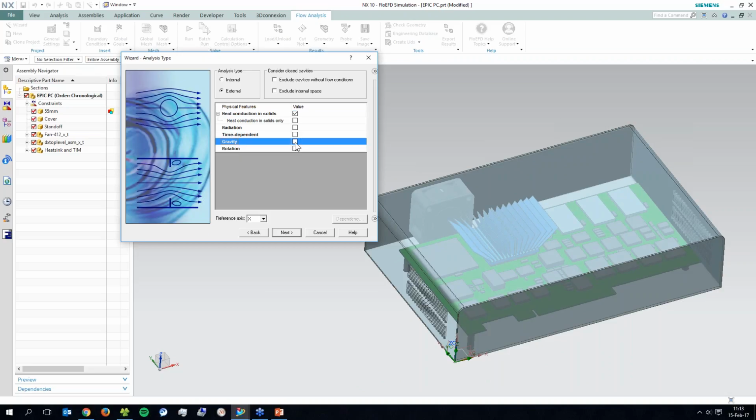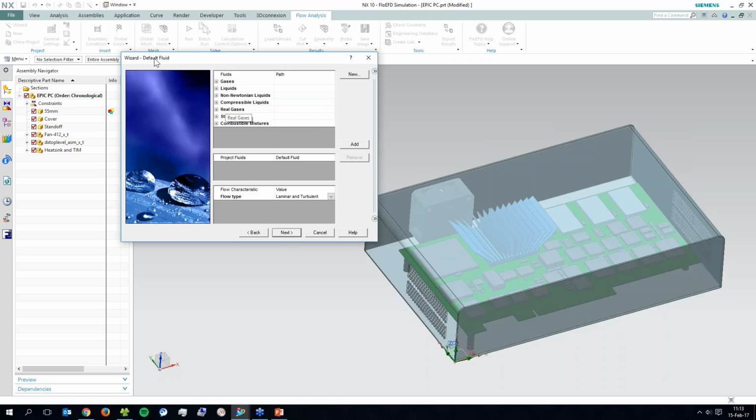Okay, I can set gravitational direction for natural convection purposes. I just need to change the direction to the Z direction like this. Okay, and you can see gravity going to be acting in that direction. So these are the features I'm going to turn on for now. My working fluid is going to be air, so I double-click that and put that into our project. And my default solid, let's choose aluminum, for example.